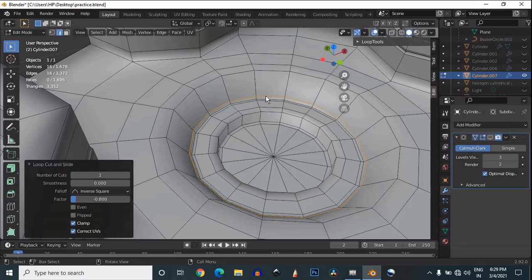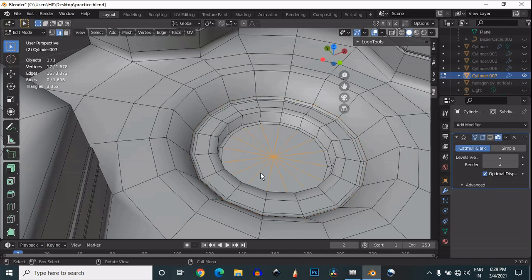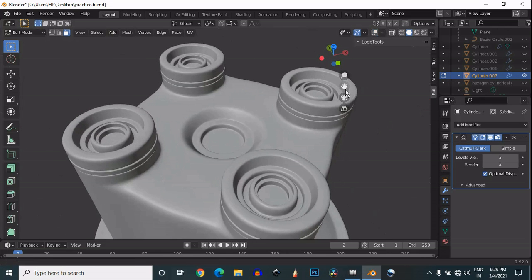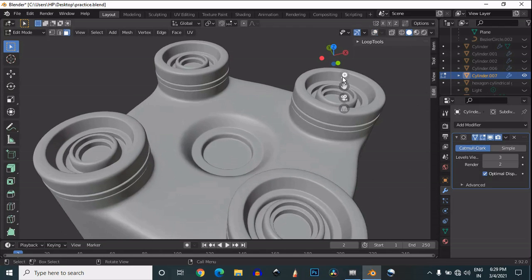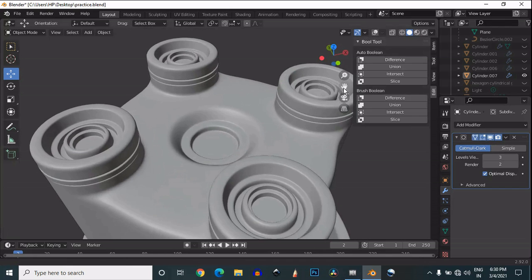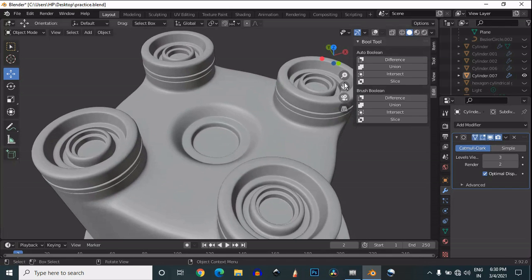Then add loop cuts to tie these edges to maintain the shape. Then select these edges, and then you can create the quad based geometry right there also. So just use the same technique, connect vertex path, shade smooth it, and then turn on and turn off that subdivision surface modifier to see your mesh, its shading.